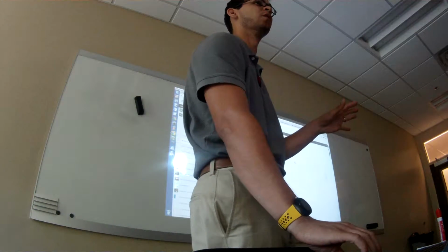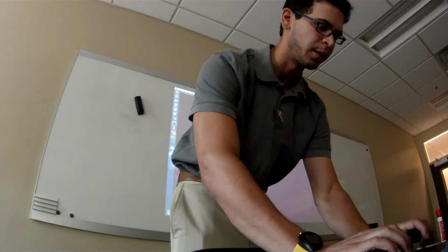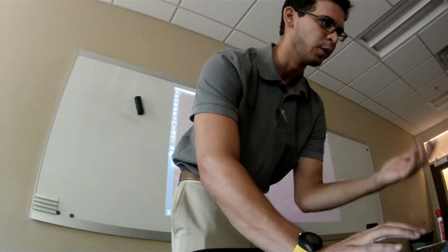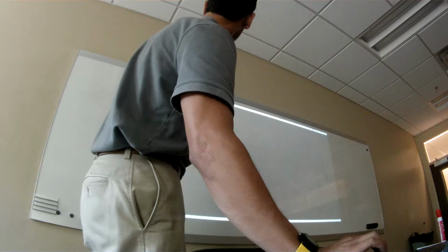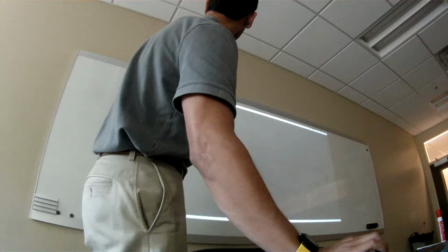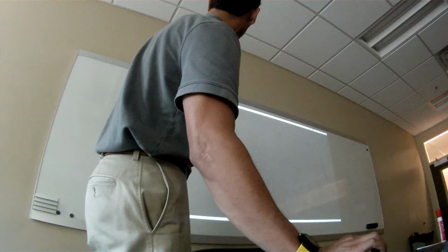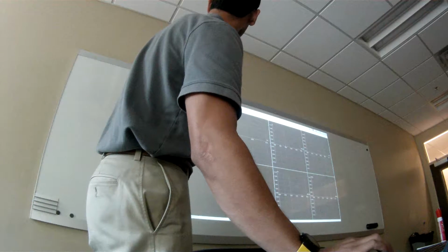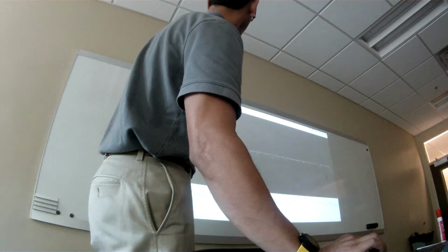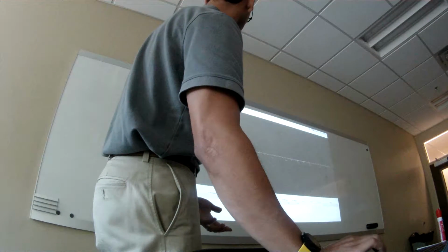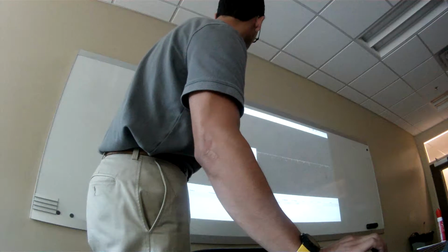I'm just going to show you a quick 2D airfoil analysis. So I'm in Linux, so I'm going to type in XFLR5. In Windows, it'll probably be a little bit different. It's going to bring up this black window. So if I head up to File, I'm going to do XFoil Direct Analysis. Oh, that's not what I wanted. Direct foil design. So I'm going to design my airfoil first. I'm going to right-click. Again, this is all in my tutorial. I just kind of want to show you.